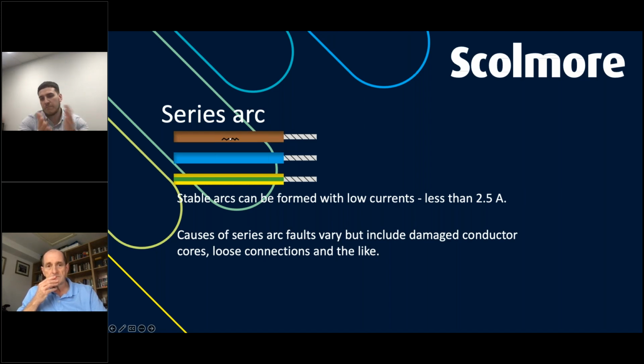So we've just mentioned a little bit about where we're looking at socket outlets when it comes to this. Typically speaking, everybody uses ring final circuits, but you can't actually get the fault that is needed, the high resistance joint, to generate a series arc fault. It will choose the path of least resistance, it'll go back around the other way.